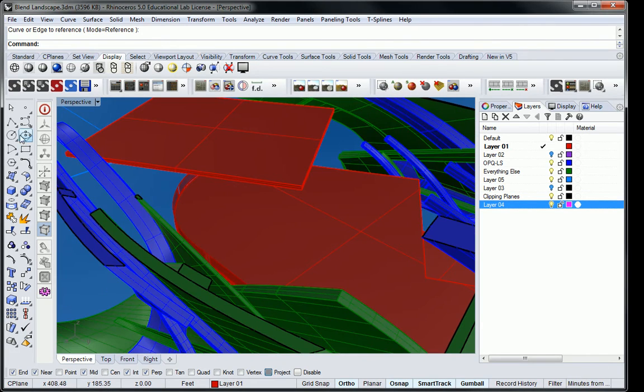If you're creating a stair, you need to think about, well, what is the slope of the stair? How big does it need to be? So generally, rule of thumb is a minimum of 4 feet. For schematic design, we tend to just say 4 foot for the width of a stair. That's a good ballpark. Or if you need to go wider, that part's up to you.